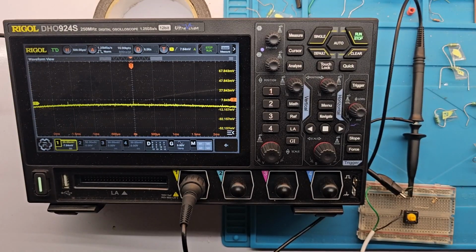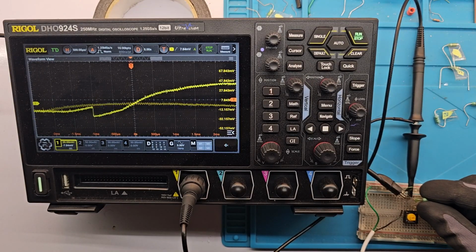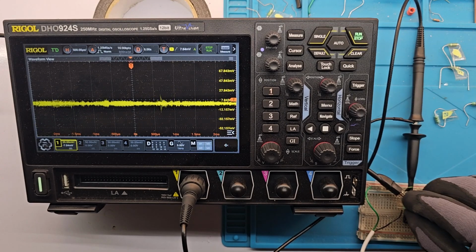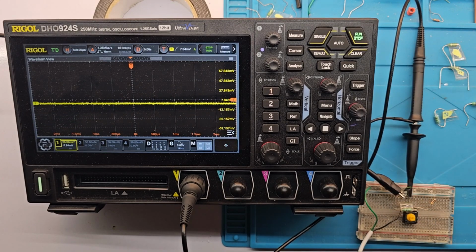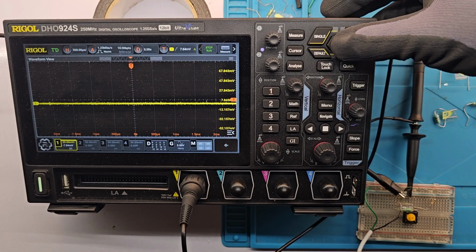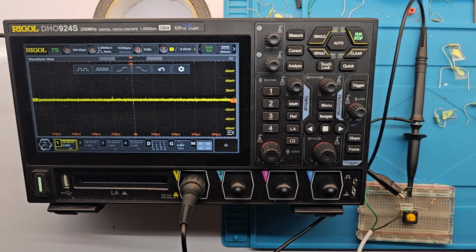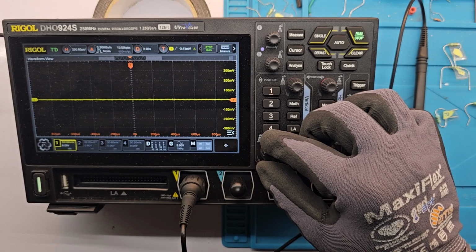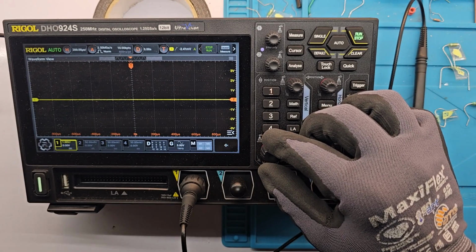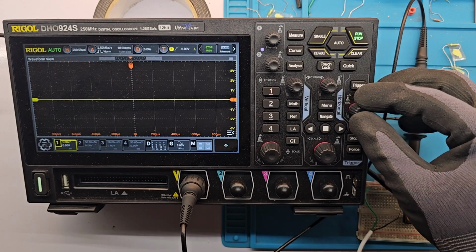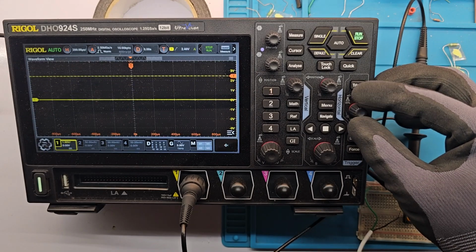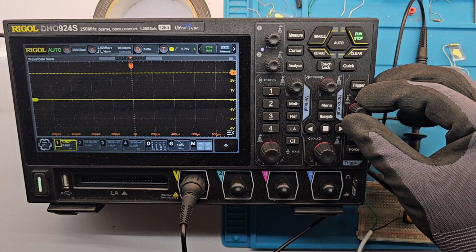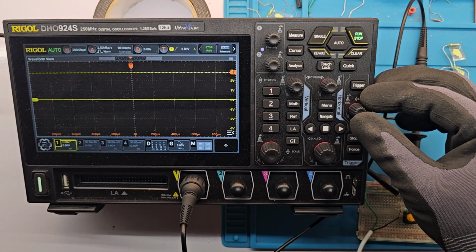Okay, so now let's install the inductor, the 1 millihenry inductor here, and then my power supply is connected, and I press auto. This is the normal signal which my oscilloscope is seeing. It's in the range of millivolts, so I'll scale it down to see at least 1 to 2 volts. With this I'll set my trigger to 3 volts. But this can be experimented with, in fact.